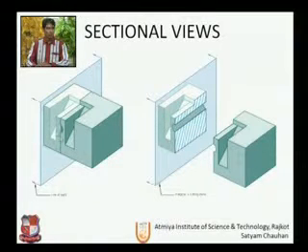So this is a complex geometry. We are cutting this section over here to represent the inner views of it, and then we are drawing this view as a front view. That will be called a sectional front view. And whatever cutting takes place over here, we draw with the help of hatching lines. We will see what a hatching line is and how we use this cutting plane in different ways.